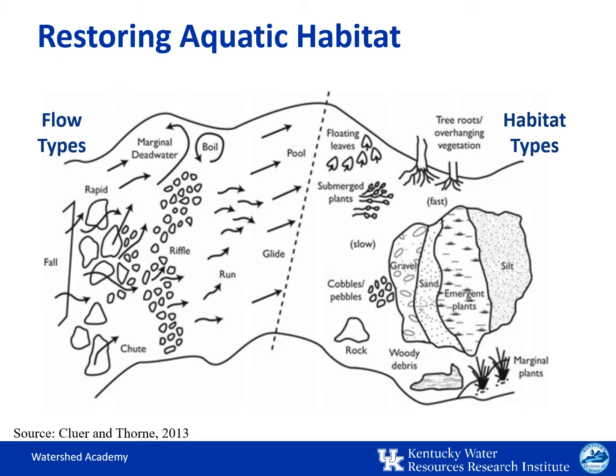You might recall from Module 2, we looked at how the varying depth, velocity regimes, and flows in the water provided ideal habitat to increase aquatic diversity. So this includes riffles, runs, and pools that can be colonized by different aquatic species. And so when seeking to design habitat enhancement structures, it's important to consider all of these in-stream components, as well as a healthy, well-vegetated riparian zone.